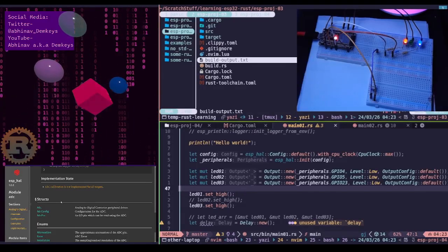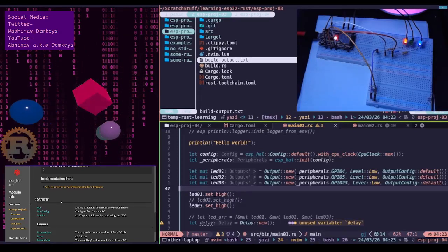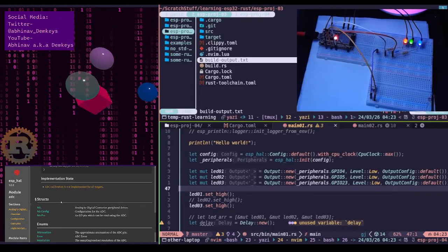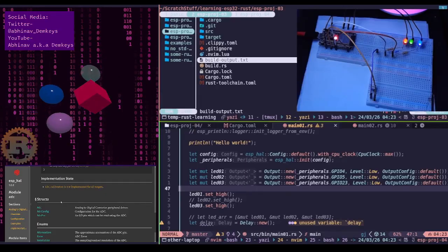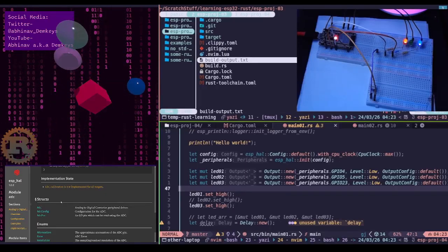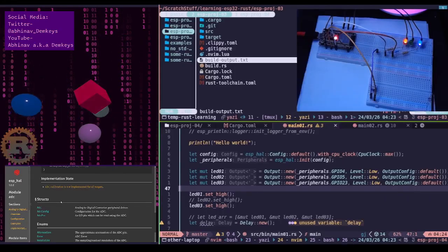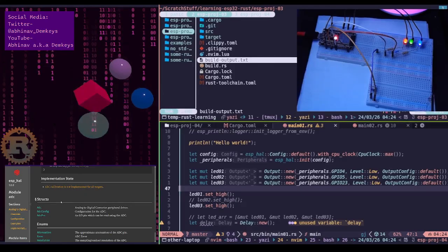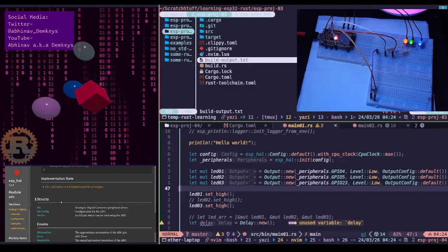The output value is usually 12-bit, unless you manually change the bit width, and the voltage input is usually 0 volts to 2.5 volts. If you try to measure the 3.3 rail directly, you'll notice the value stays at 1495 for a large chunk of the upper voltage range. This is called saturation. Okay, good to know.